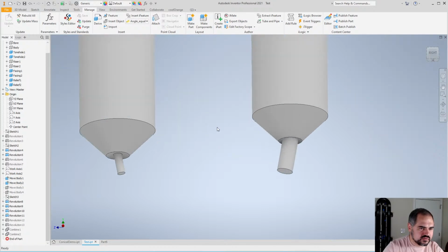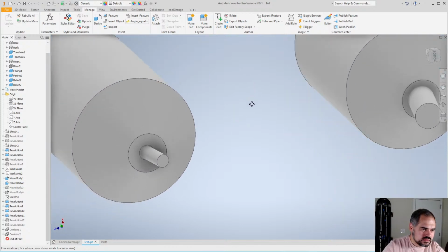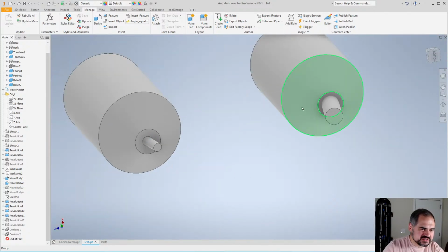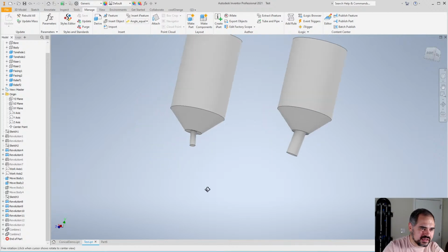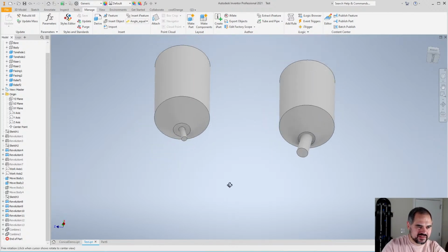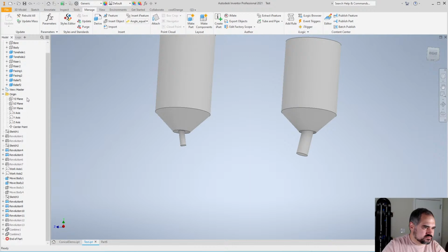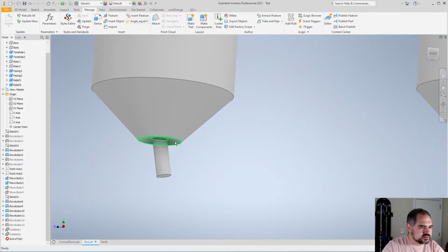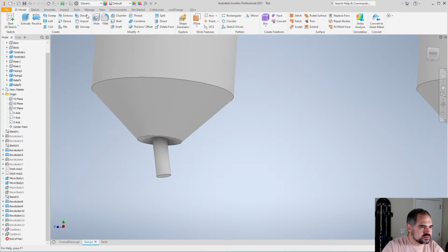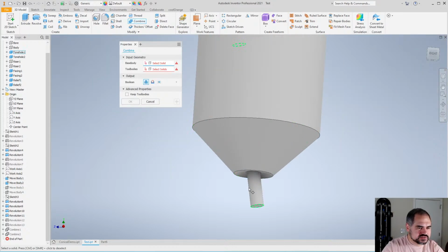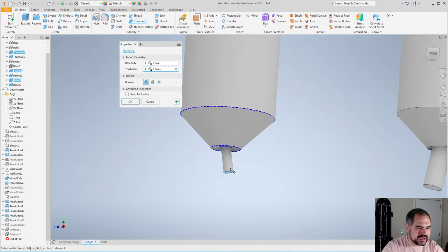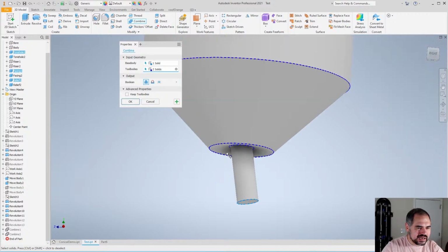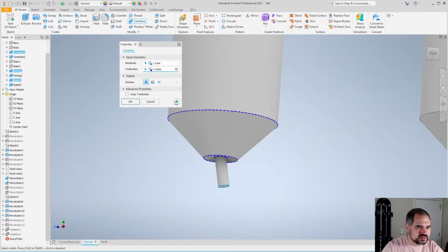Flip that, flip that. Okay, so now our tone holes intersect with our facings the way that we expect them to, our angled tone holes with our perpendicular facings. Okay, got that fixed. So let's merge. We're going to use a combine again, and we're going to combine our tone hole with our facing and our relief, and we're going to keep that on join.